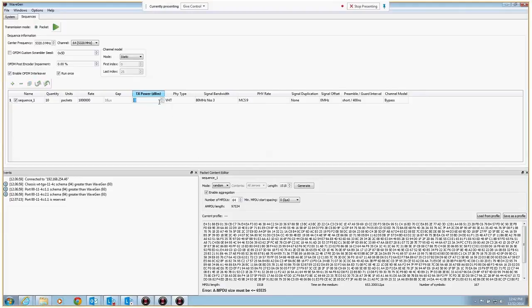Is it a signal power problem? So you can simply change the signal power and run it again. Go look, did you get 10 frames? Oh, well, maybe that wasn't it. Maybe you're concerned that it's a PHY rate problem. So you can very simply go here, change the PHY rate. Now you're running again. Gosh, that didn't work that well. Let's go back to MCS 9. Let's try 2 spatial streams, 80 megahertz. And off we go.